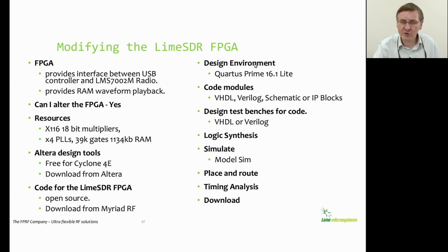And then it's just a matter of using the Quartus design suite with VHDL or Verilog or schematic and IP blocks. Design your test benches in VHDL or Verilog. Do a logic synthesis and simulate using ModelSim, and then carry out a place and route synthesis, and do a timing analysis and then download to the SDR.